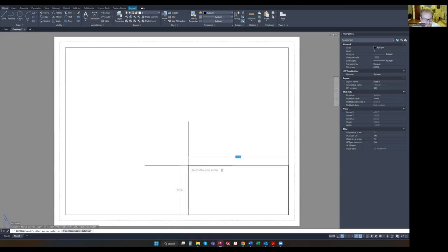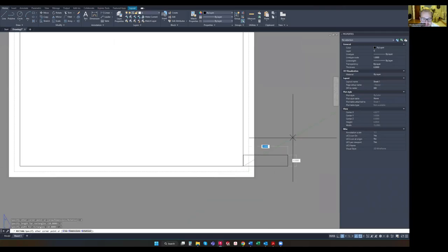And what that means is if I type D, enter for dimensions, now it's asking for length. So we're going to type 2, enter for the length. Then it prompts you for a width, and we're going to say 0.5, enter. So now we have a 2-inch long by 0.5 high rectangle. And at this point, it's going to ask you to snap it to a point.